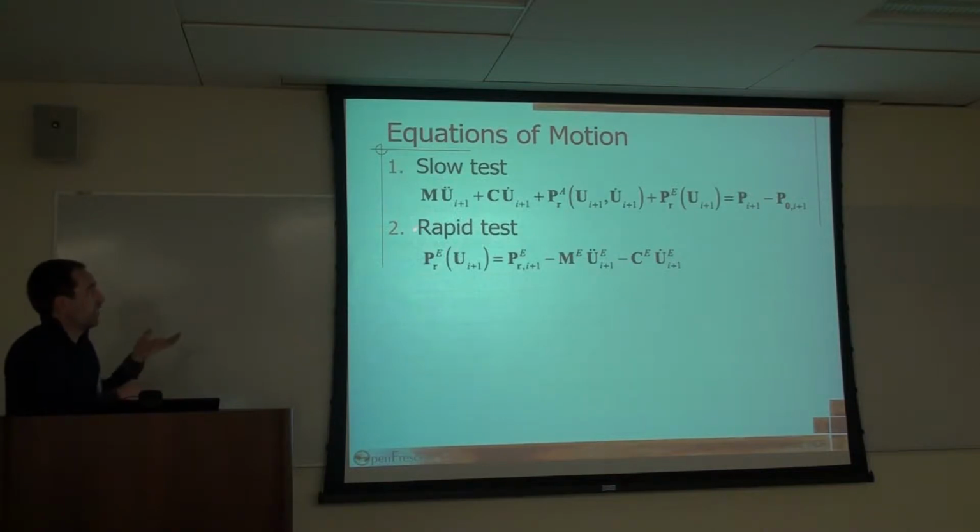To make this correct, we can measure accelerations and velocities, and we can correct the forces that we measure from our load cells. We correct those by the measured accelerations and measured velocities, knowing what the mass and the damping are. The damping might be a little tricky to know, but we correct the measured part before we feed it back into our analysis, right?